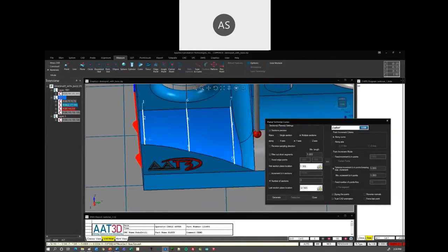All right. The next thing I'm going to do is I'm going to say fixed number of points. So how many points do I want in each of these cross sections? I have 3 options. I can either fix the increment between points, so take a point every 5 millimeters. If I know that my surface is changing, I can choose the optimization function, which will say put the spacing at 5 millimeters, but if the direction or the curvature of the surface changes, reduce the spacing between the points to give me a higher density of points on surfaces that have more curve to them. Okay, and then the last one, which is my favorite, is just give me 5 points. And this is going to be 5 points per cross section.